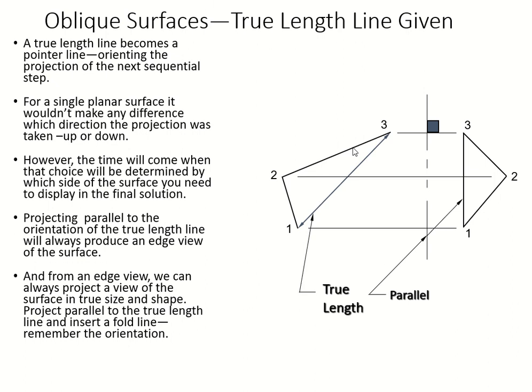So you have to think about which way you're going to draw, even if we're trying to get the top view, because you're given the front and then the right side view. Since this is a front, right view, and your parallel line is on this side, we're getting the true length on that side. Therefore, we'll have to project it from this side to the top view. So I would just go in this direction to get our next edge view. So let's take a look at how they do it.